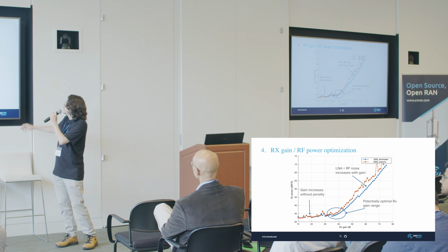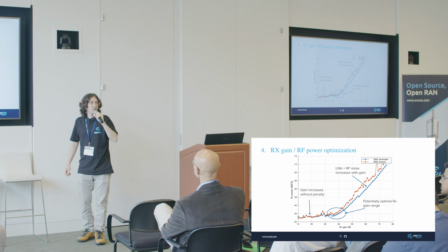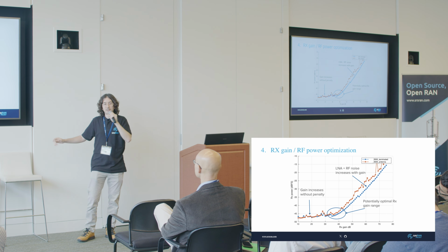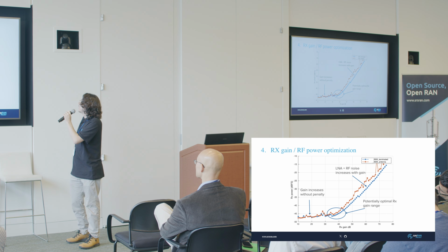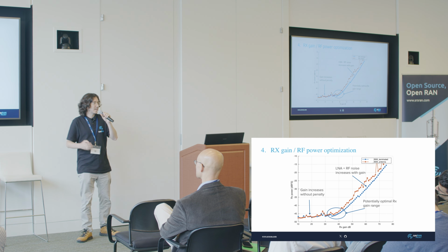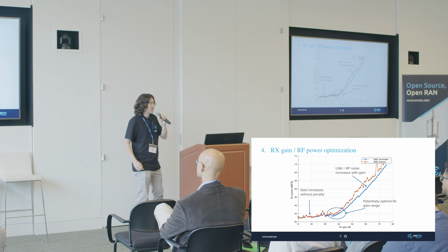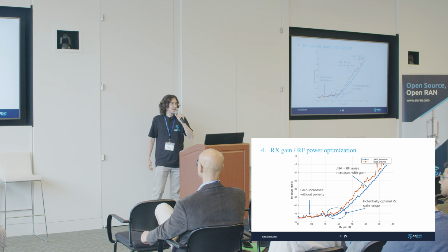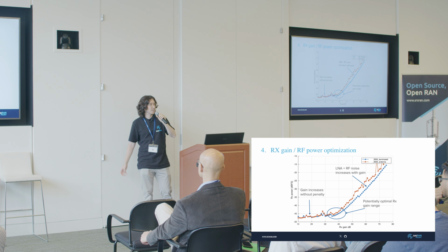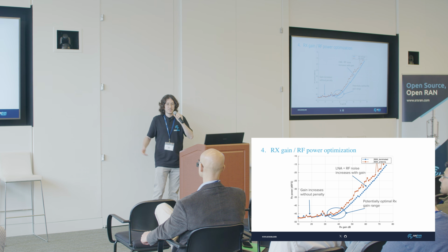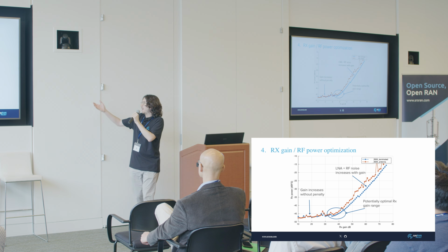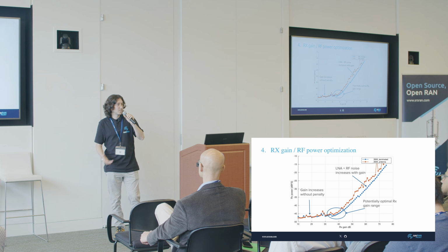The blue line is the power measurements when we terminate the receive port, so this is only internal noise. And the red line is measurements with an antenna. In this case, they look much more similar, no? Well, this is band 79. Of course, in band 79, there are no commercial gNBs, at least in the place where we did these measurements. And what this means is that the interference is way less prominent.